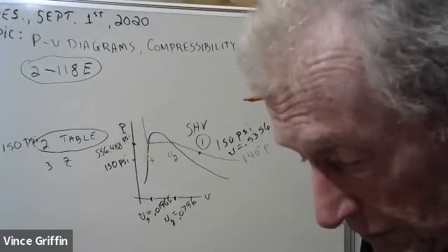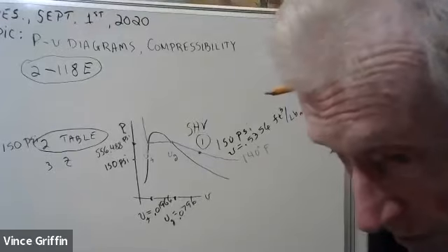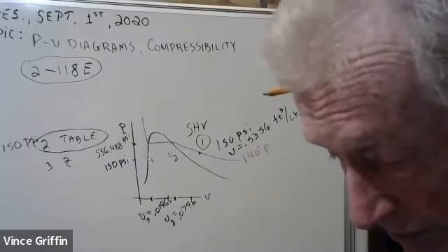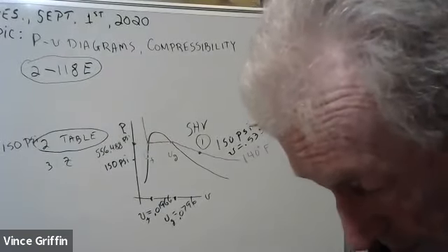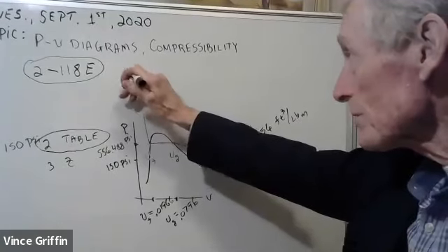And I just want to make sure I understand. So you started with a saturated table so that you could find that your state one was outside of the vapor dome. Yes. And that's important because then that took us to the superheated vapor table, and that's where we got our answer. Okay, all right. Yes. Good going.